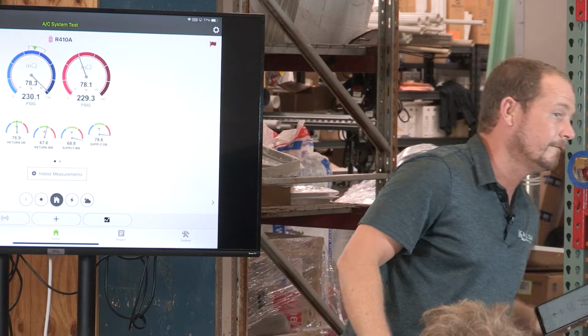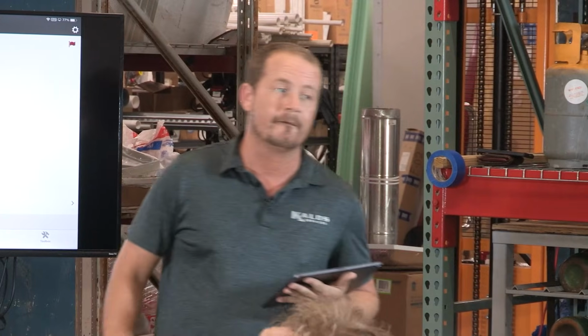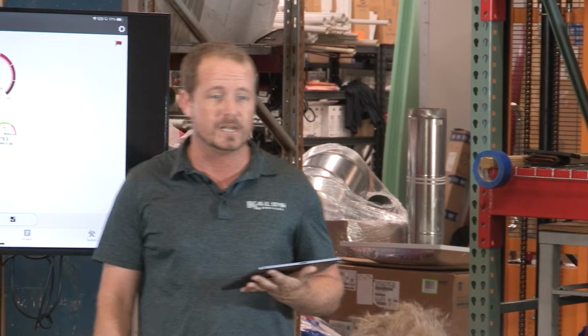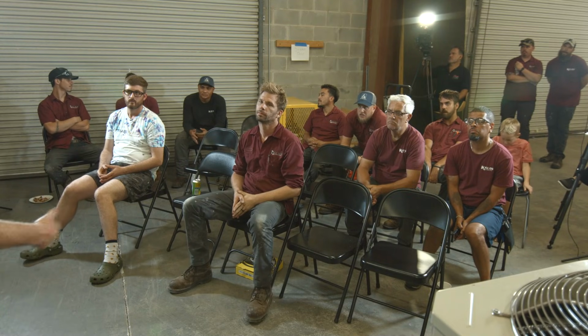Because you have liquid refrigerant going through. You're not absorbing as much heat. Because you're not picking up as much heat, right? If you don't have enough air, you're not picking up as much heat. And so that drives down the evaporating temperature. So your evaporator coil gets colder.